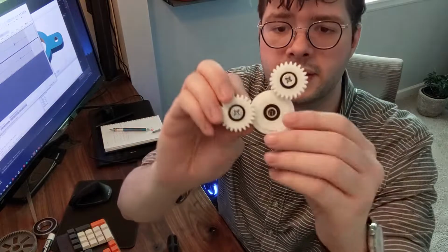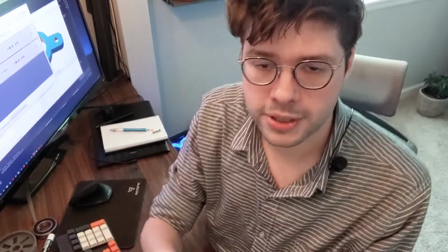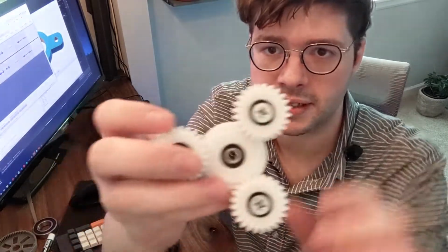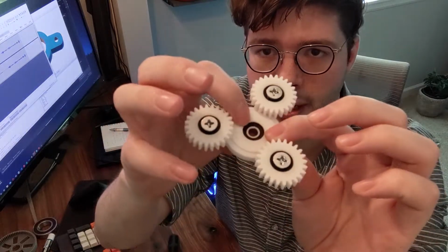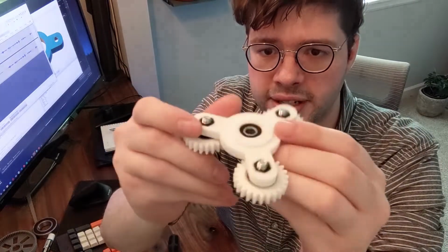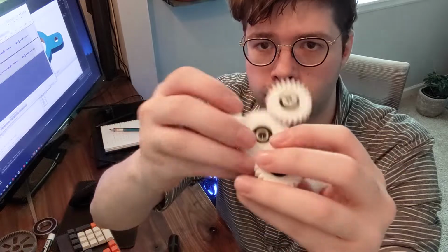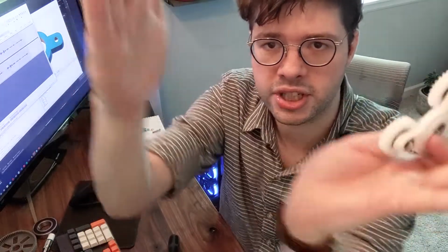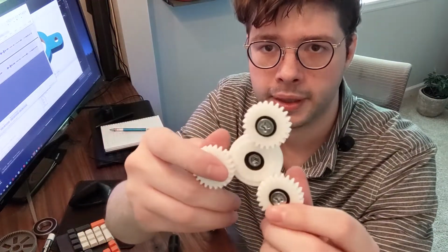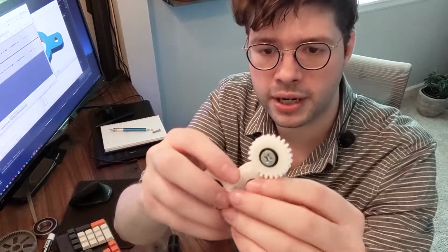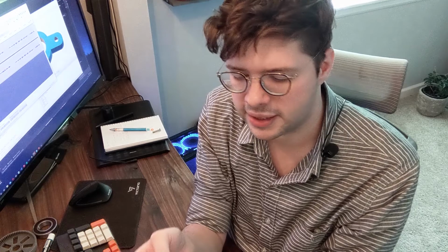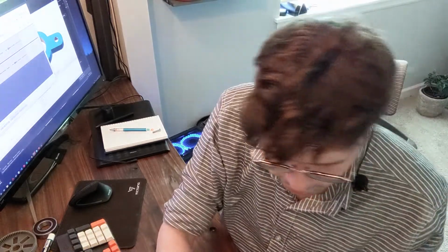So we have this. Another interesting aspect of this design is that the arm itself has to have a bearing. So to solve this, I have 2 different caps, one on either side, which sandwiches the bearing together. And they have a strong enough tolerance that it's not going anywhere. I do not ideally enjoy this design. I think I will revisit this shortly. However, it is too difficult to take apart at this point, so I'm just going to roll with it for now.